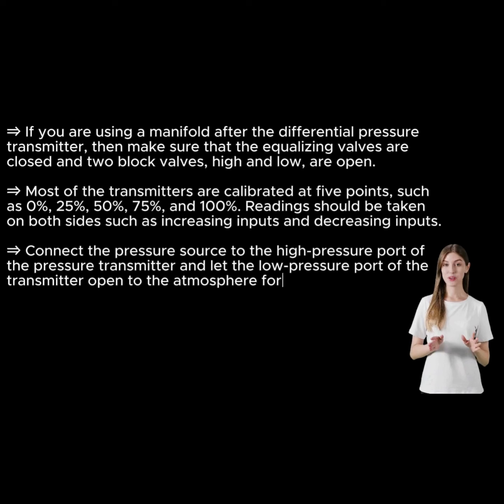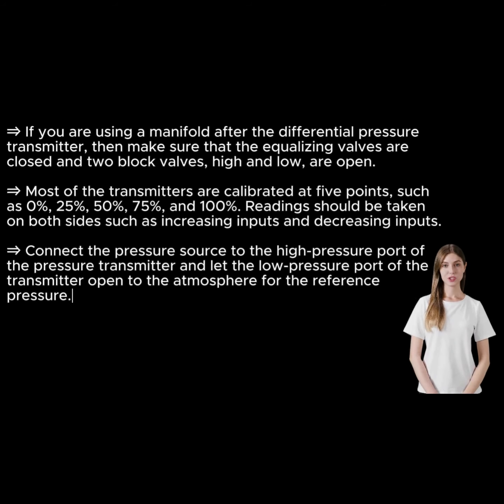Connect the pressure source to the high pressure port of the pressure transmitter, and let the low pressure port of the transmitter be open to the atmosphere for the reference pressure.